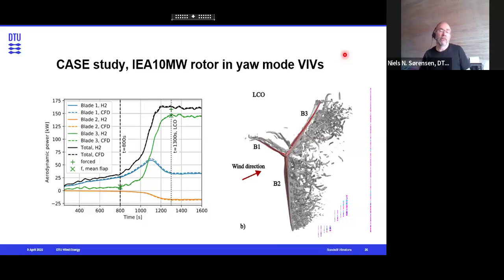The regions where we hear a lot of fear from manufacturers are during erection, for example. If you have 1, 2, 3 blades on the turbine and it's not grid connected, then you're really badly off. And often you wouldn't, even if you had power on, be allowed to yaw the turbine if there's a crane close to the turbine. So that is a really bad situation. Another case could be if you have a grid problem, so you're not connected to power and can't position your turbine.